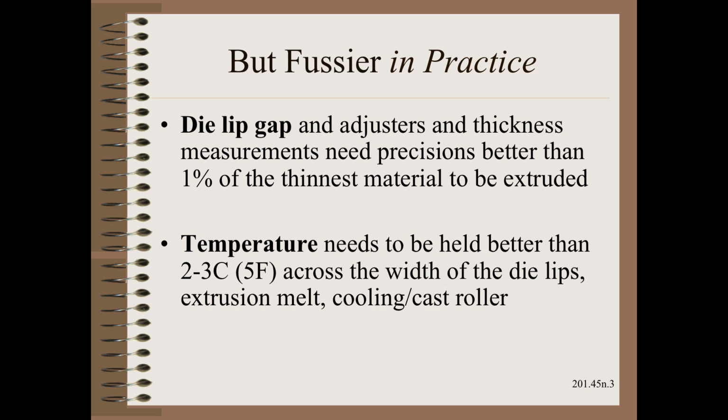We may need to hold temperatures of the film and everything the film touches to a few degrees to avoid thickness profile problems, and thus bagginess upon winding. While temperature is important for paper drying, it is not quite as fussy. In the next slide, we will introduce a challenge that is common across all the web industries.